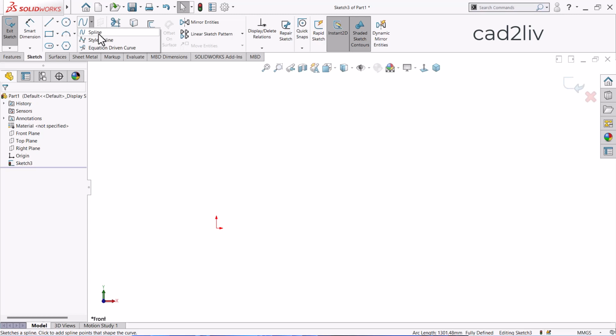You could eliminate that part regarding the Bezier, because that is going to get into detail in surfacing. Like in surfacing, we may have to use the Bezier splines to trace the surface. Okay, next one is the equation driven curve, which is a very useful tool regarding how to use equations to get the line in the graphics window. So this completes the tutorial of this spline.